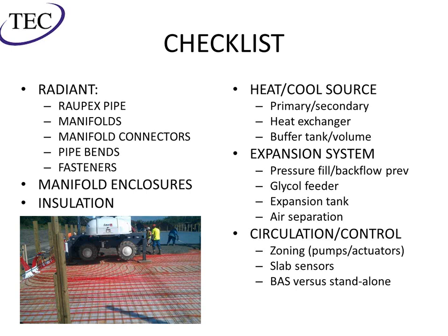This is just a cool little photo on the side here. They've installed the radiant actually between two pieces of mesh. They installed a piece of mesh, used nylon ties to put it down, and then put another layer over it for the concrete because they're using a thicker slab. And as you can see, they got that big laser screed on there, smashing down the pipe, no problem, super resistant. But you want to make sure that you're accounting for all that mesh, all the fasteners, and then as you can see over on the left, got the manifolds there to keep it under pressure, and the pipe ends.